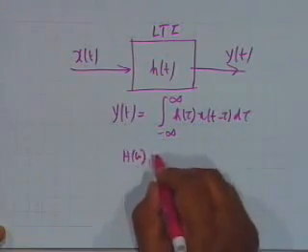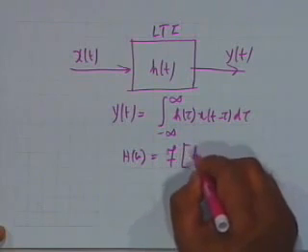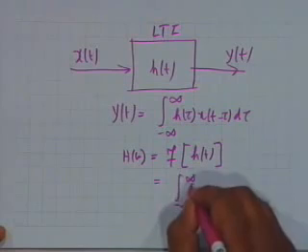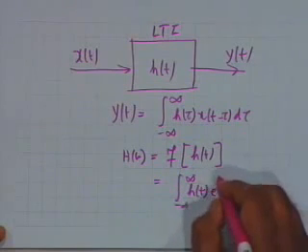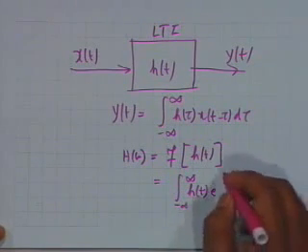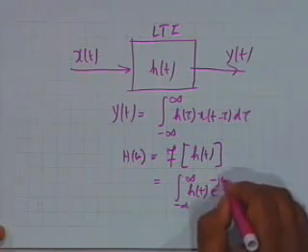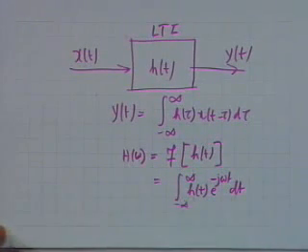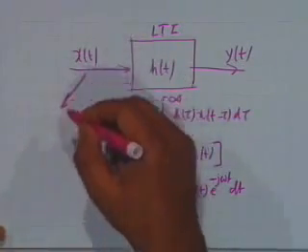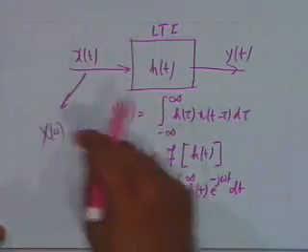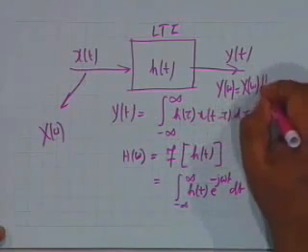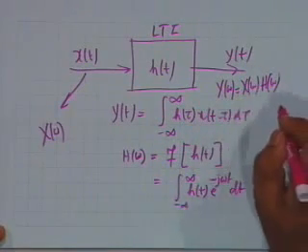What you do is take H(omega), which is the Fourier transform of h(t). That is, the integral from minus infinity to infinity of h(t) e to the minus j omega t dt. You take the Fourier transform of the unit impulse response, then you take the Fourier transform of x(t), multiply the two, and you get Y(omega) as X(omega) H(omega) in the frequency domain.